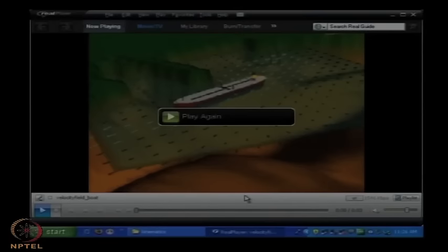So it is not a direct visualization, but you may do it in two ways: by post processing the visualization of the particles which are injected into the fluid, or by doing a computer simulation, and sometimes these may be equivalently compared. Computer simulation of course is an idealization, because you are using certain boundary conditions, certain properties which might not exactly prevail in reality, but sometimes it gives a very important idea of how the fluid flow is taking place, and it is used for advanced designs also.